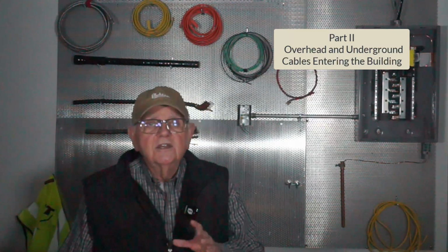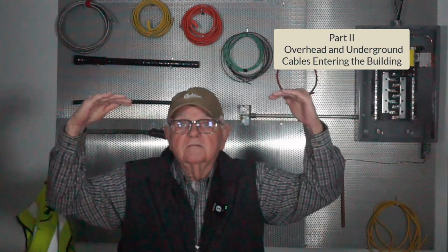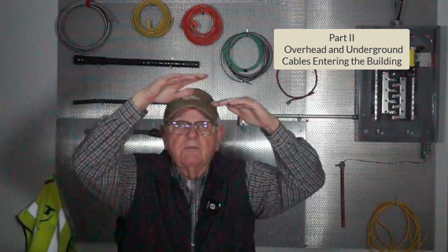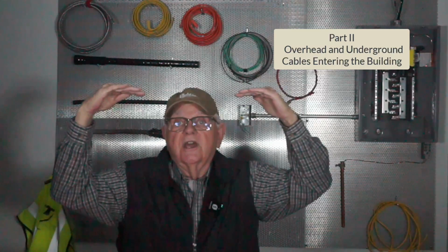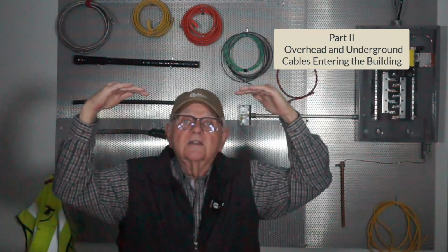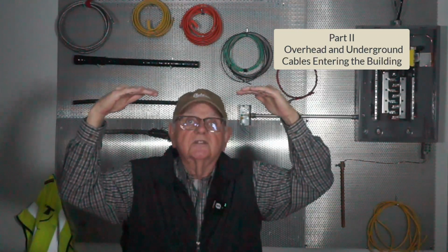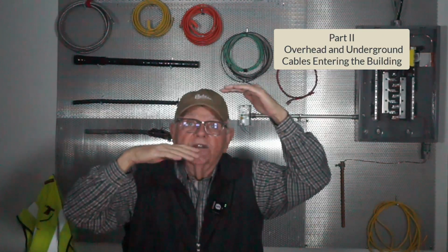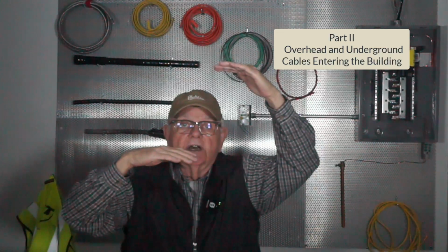On overhead, and you probably don't get into this, or some of you do, I'm sure, but if you're going up on a pole and you've got that cross arm up there, only those light and power conductors are going to be on that cross arm. Any of that communication cable, that fiber optic, is required to be below that. The distance is based on the voltage of my overhead conductors on the cross arm, and I can't ever attach that fiber optic cable to that cross arm.